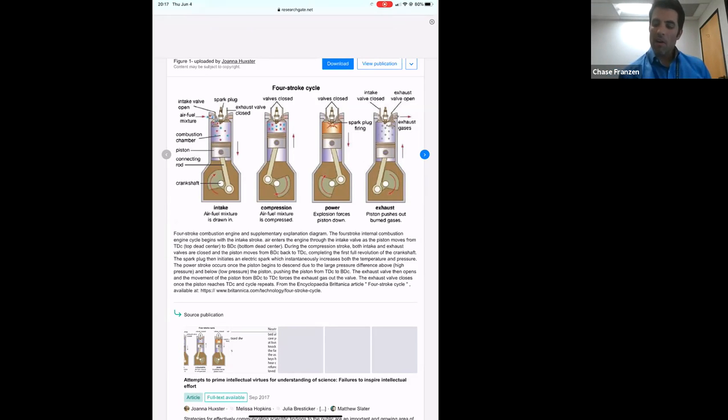So the engine is air-cooled, meaning it's not water-cooled, and it's not necessarily the entire engine oil-cooled, it's air-cooled. It's naturally aspirated, meaning that some aircraft engines use compressed air in the induction cycle, which I'll explain in a second, by way of a turbocharger or a supercharger to really compress that air. This airplane does not. It breathes normal atmospheric air, just like you and me.